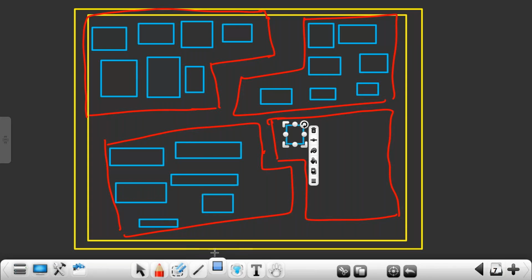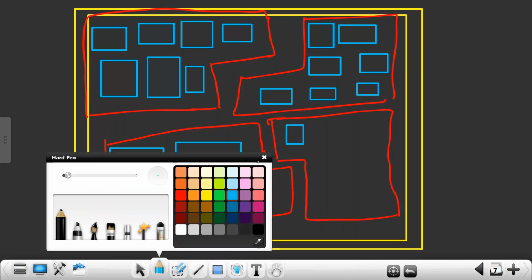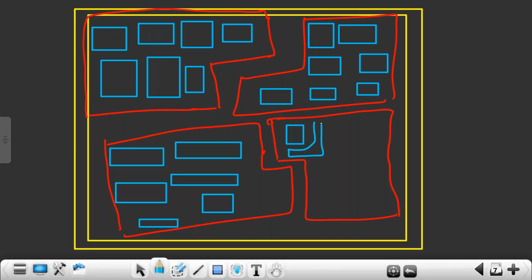So each block need not always be the same rectangle shape. It can have even an L shape, even it can have a U shape. Right here, you can adopt one more block. So you may have any shapes. It's not always a rectangular shape. So first this full chip is divided into what? Subsystems. There will be a full chip team separately. They are working only on the full chip, dividing this full chip into different subsystems and interacting, managing the connections between subsystems.